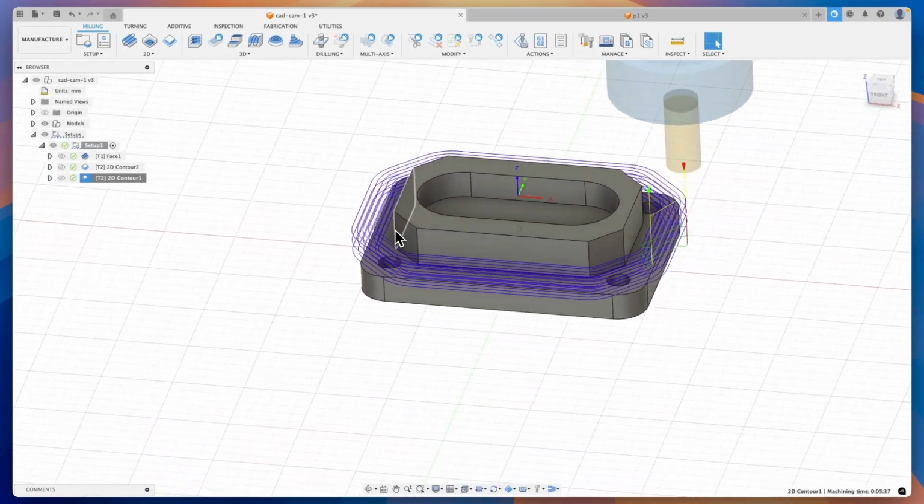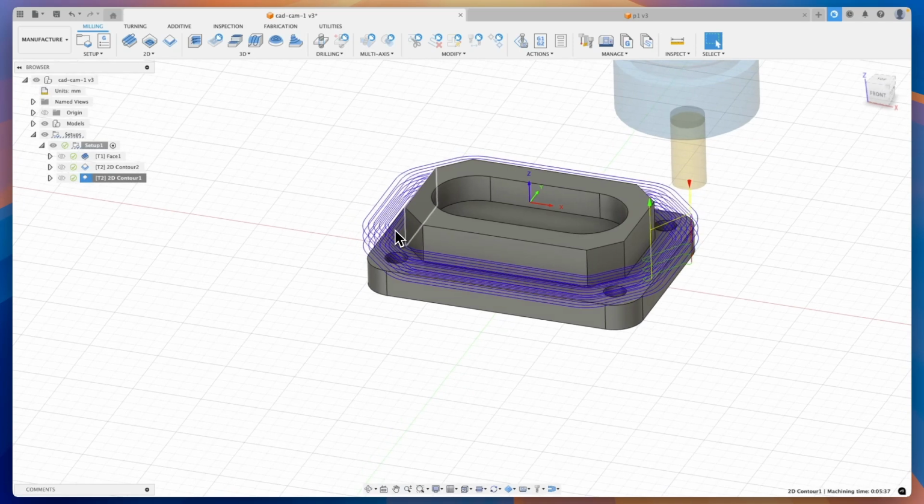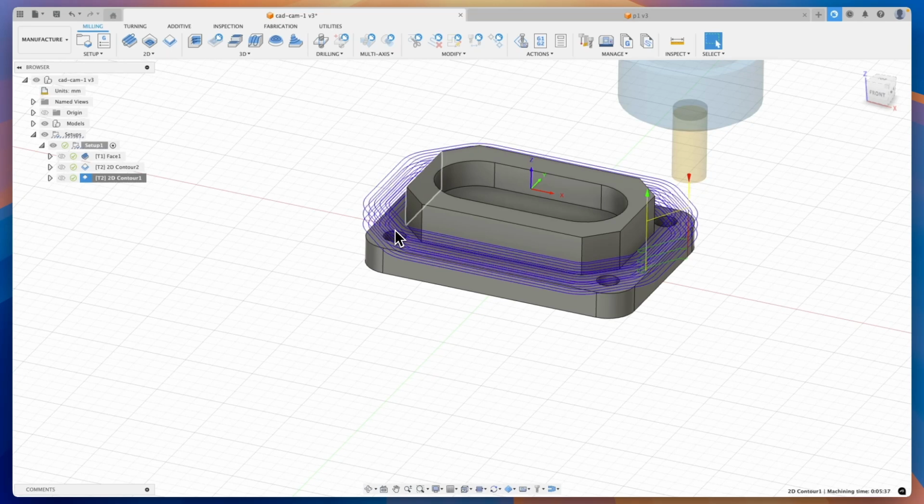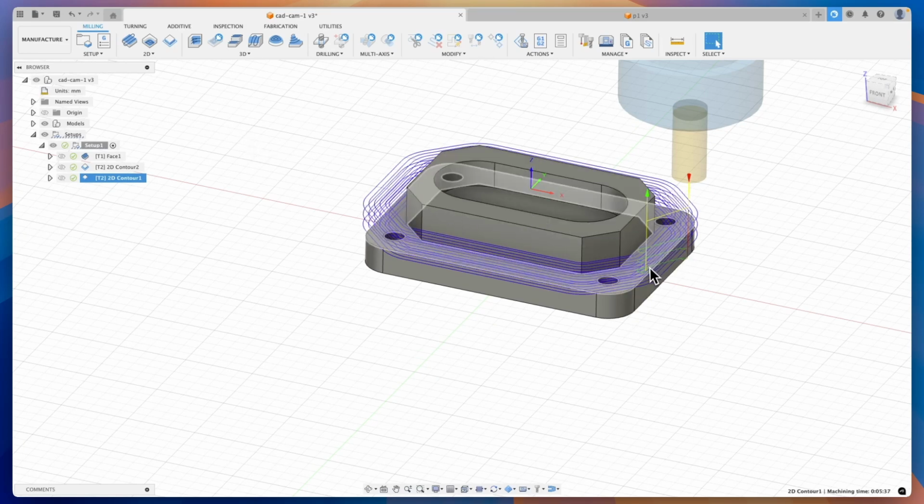Of course, here I want to show you the principle of these parameters, so you know where to find parameters that allow you to determine the number of passes in the Z-axis and the number of passes in the XY axis, so we can make this machining a bit gentler so it doesn't overload the tool and the machine so much. We simply adjust this to our own capabilities. As for contour machining, it's worth paying attention to the parameters regarding the tool's entry and exit.